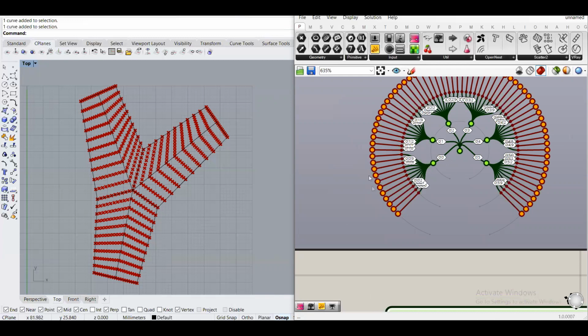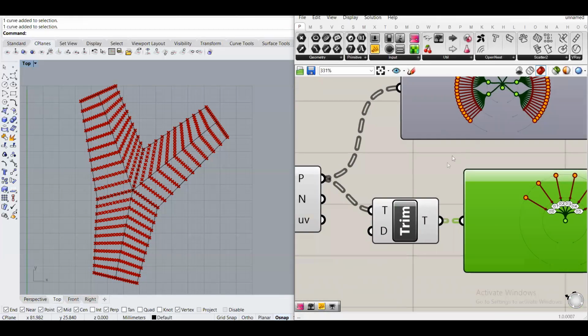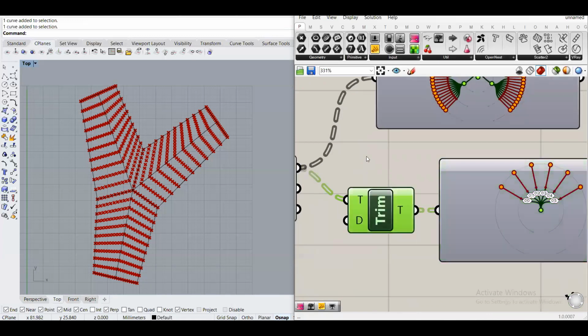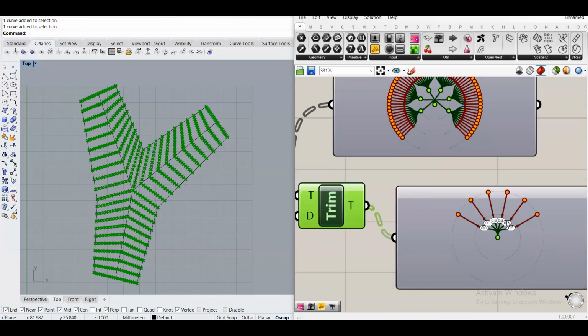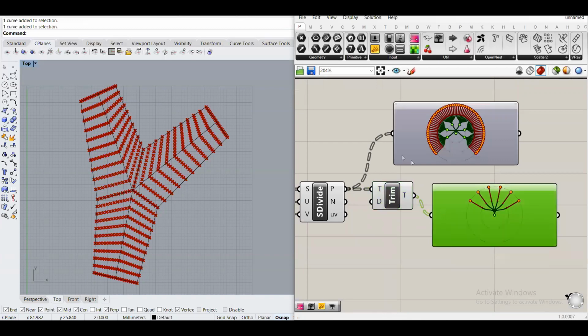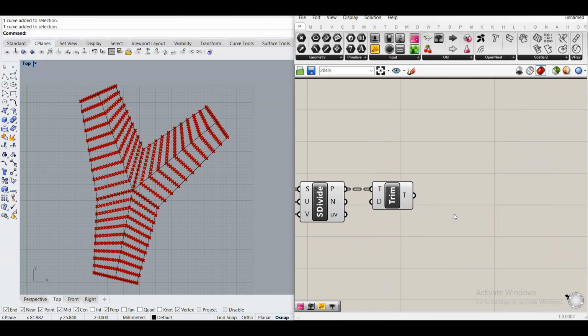We don't want those points to be divided up into rows, which means we can use this tool that's called trim tree and get rid of that row and column information in our grids, right? So that's why we're using the trim tree, and we are only left with six lists of points, rather than 66 lists of points. Okay, time to make a mesh, I guess.